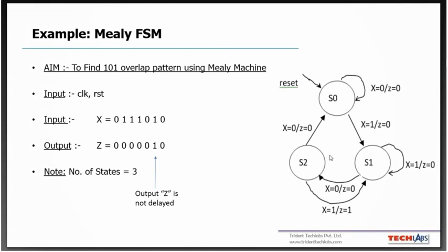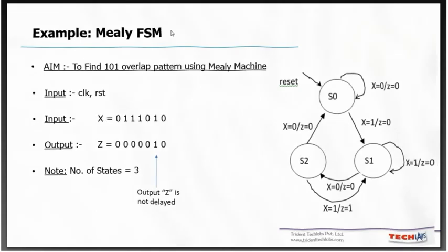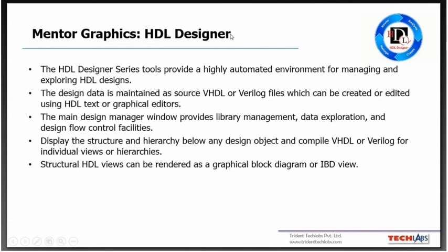So now coming back to our HDL Designer. HDL Designer is a Mentor Graphics package that is available with higher education program too. So what exactly is HDL Designer? HDL Designer tool provides a highly automated environment for managing and exploring HDL designs. That is nothing but we can analyze, we can reuse, we can create, and we can manage all the files in HDL Designer itself, and we can graphically program finite state machines as well as truth tables and symbols, block diagrams, etc. All those things can be graphically done in HDL Designer.